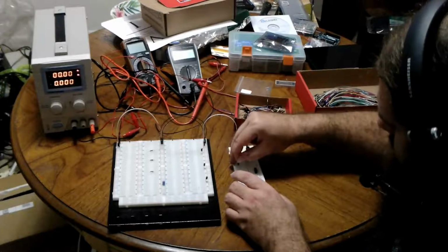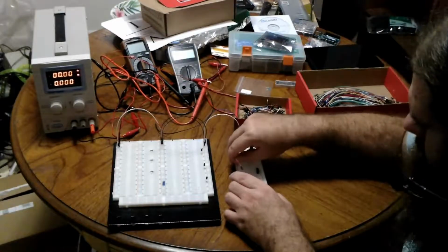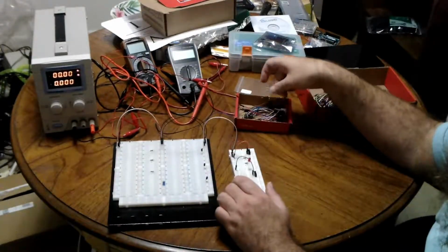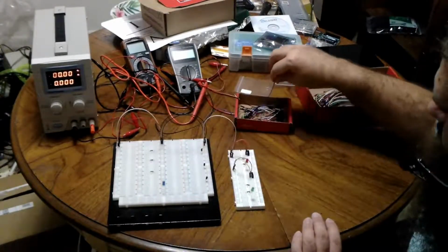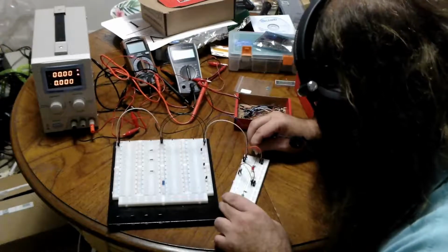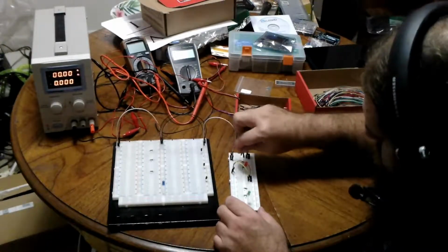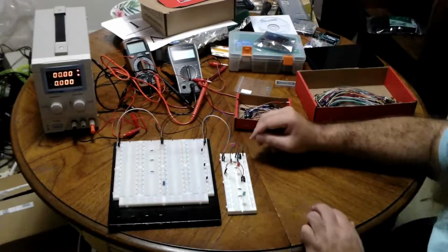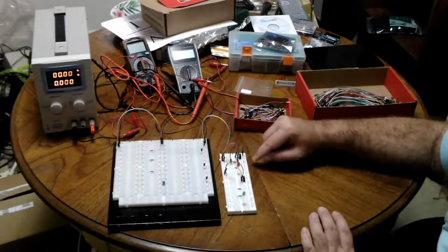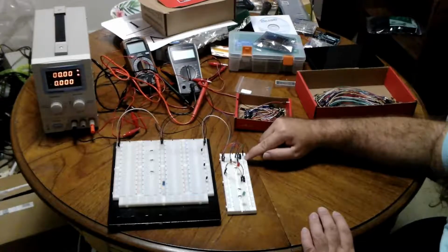So the second switch will also be connected to positive and negative in this way. So that's positive and that's negative. So that's connected to both sides of the switches. Then I'll take the middle pole from the first switch, run it through a resistor, and run it out that resistor to the positive rail on this side. That's just going to indicate input 1. So we can connect to the positive rail as input 1.